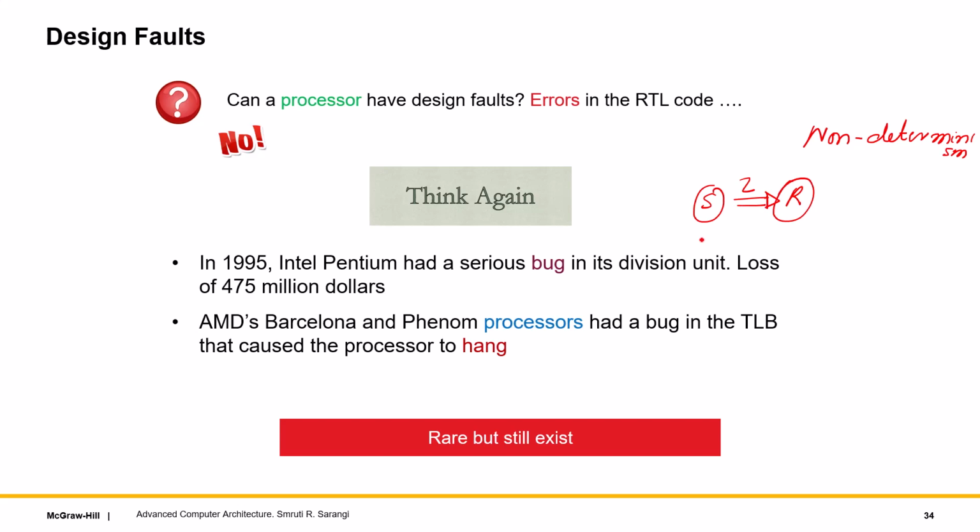The entire protocol was based on that, but in, let's say, 1 in a million cases, because of some weird combination of the temperature and supply voltage, this takes 3 cycles. Then again, this may lead to an issue or may not. But the fact is that the designer was not conservative enough. But that's of course one kind of bug.